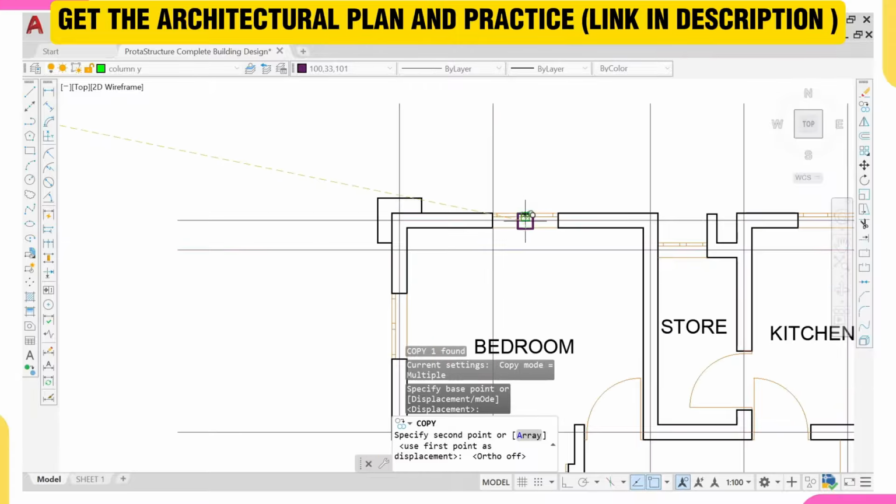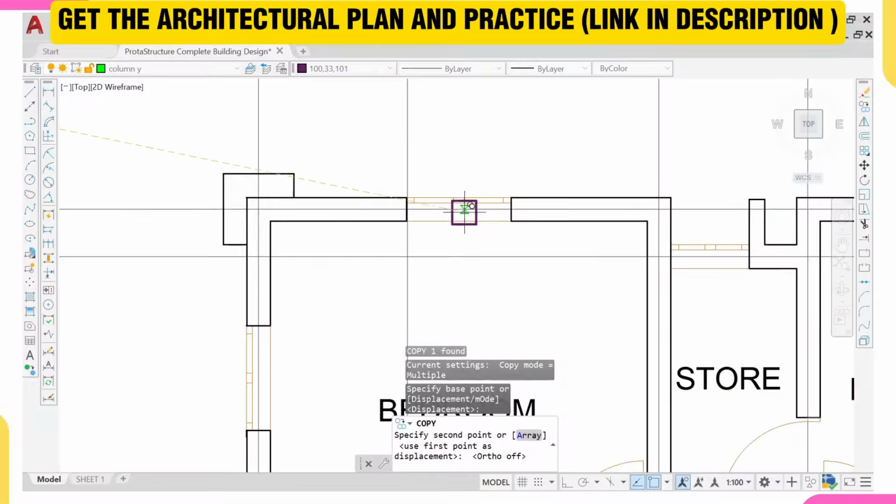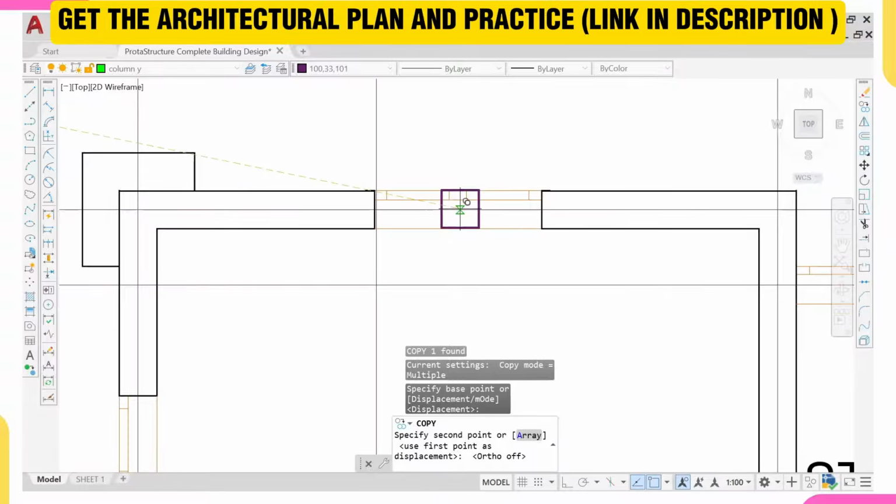Yes, I forgot to mention something. If you are deleting the things that are not necessary to us as structural engineers, please don't delete your windows and your doors. Yes, because if you delete your windows and your doors, you might mistakenly come to this point and place a column, not knowing that this is a window position.